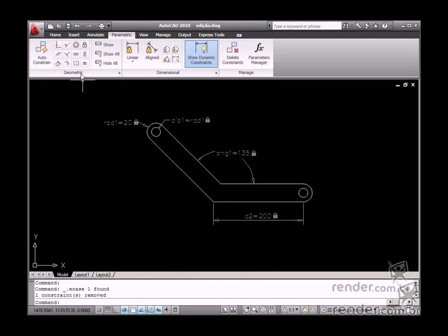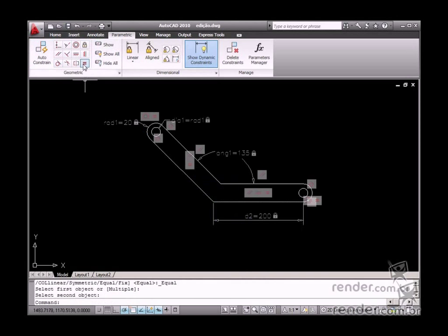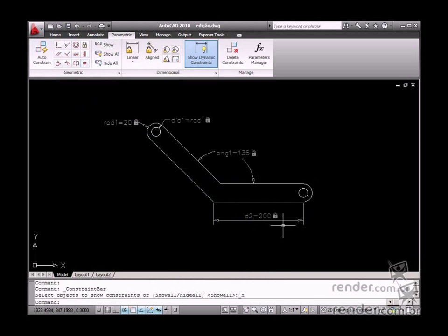You can use geometric constraints to avoid this error. You can define the same measurements for both arms by applying the equal tool to apply the equal constraint. This can help you to avoid project errors.